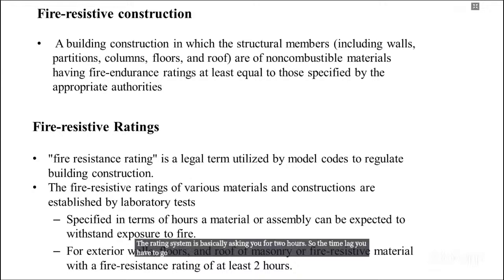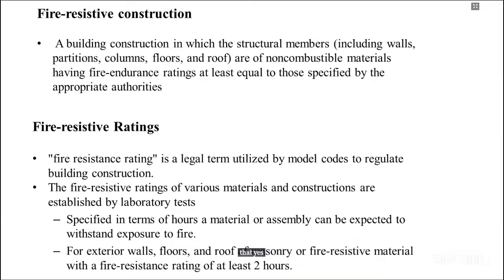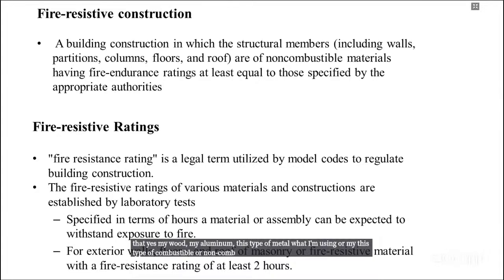So you have to calculate, you have to analyze that yes, my wood, my aluminium, this type of metal I am using, or this type of combustible or non-combustible material, maybe my brick, my stone, my RCC, is having a 2 hours time lag. So this is what is basically important in terms of the rating system in our safety rules of fire.